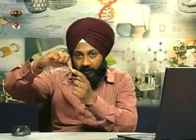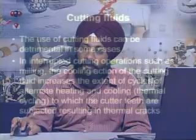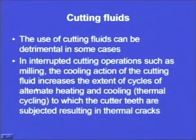Now, the tool, when it is performing the machining operation, is a multi-point tool, and it is at an elevated temperature. When it comes out, the cutting fluid is applied to the whole of the cutter. Then some teeth which are not doing the cutting operation are at a relatively lower temperature, but when they perform the cutting operation, the temperature is higher. So, in interrupted cutting operations such as milling, the cooling action of the cutting fluid increases the extent of cycles of alternate heating and cooling.